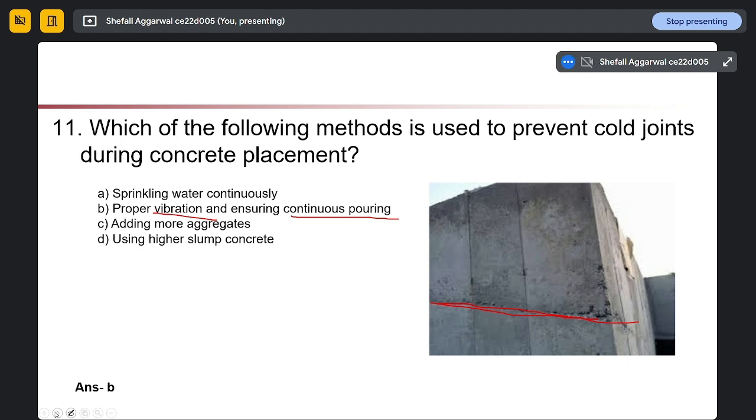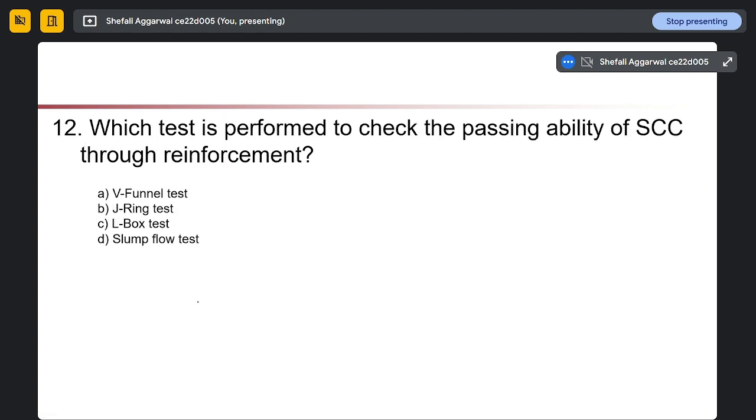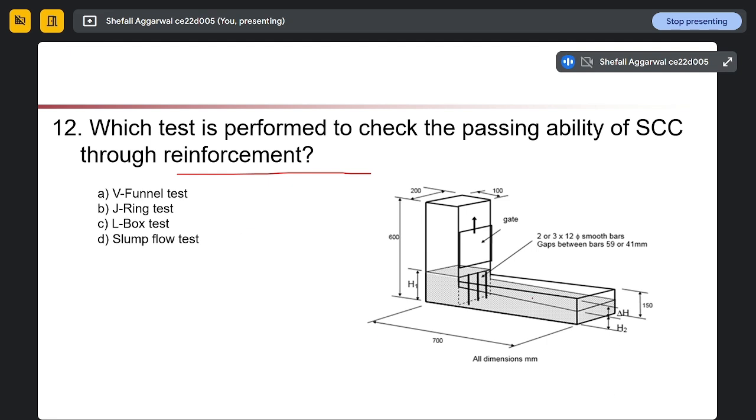Not taking type 4, ma'am. Type 4 is high alumina cement. So if we talk about type 1, which is the normal cement, we have a high percentage of C3S, then C2S, then C3A, and then C4AF. Right? So the answer is A.